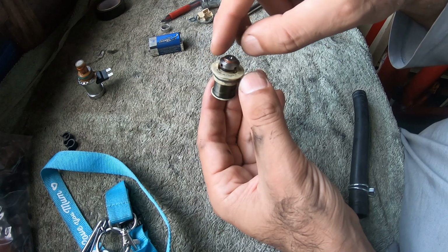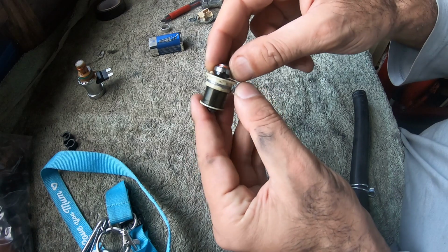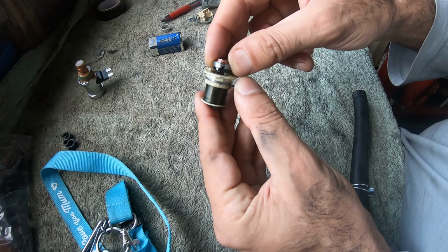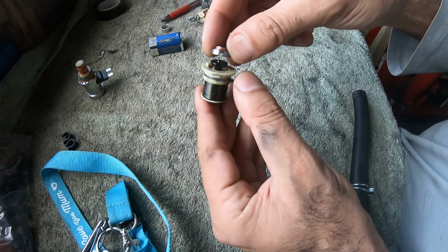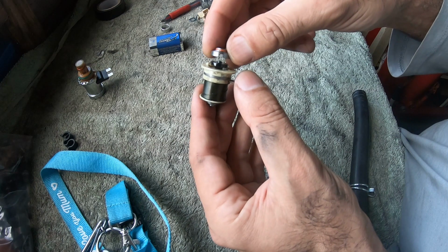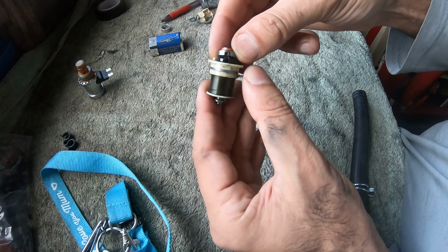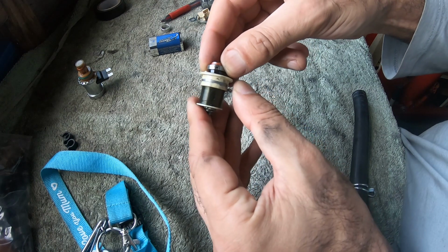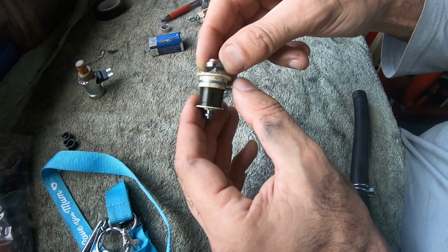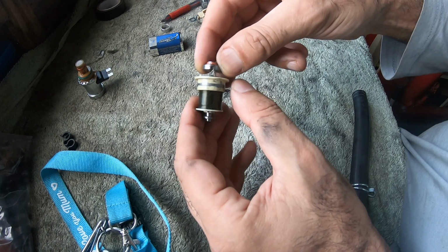Between this and the plunger of the solenoid itself, which is at the bottom, there's just a small steel ball, which I lost, unfortunately. Whenever the plunger pushes the ball, it goes through and blocks the fluid coming out. So it works like this: it blocks it, and when it de-energizes, the ball goes back, and now the fluid can go through those vents.